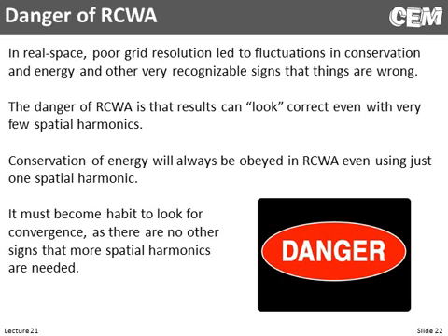Conservation of energy will be darn near perfect, and there's really no other signs. There'll be no rolling response in the spectral response because there's no reflections from a PML that would cause any kind of standing wave. So this is a danger that it lets us, or encourages us, to be lazy. And the way around this is we absolutely must look for convergence.